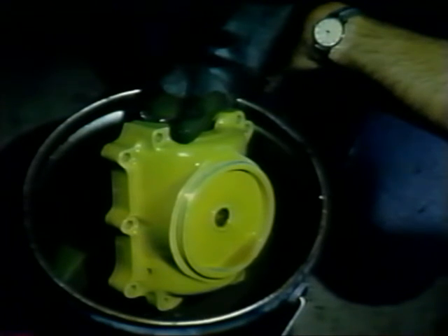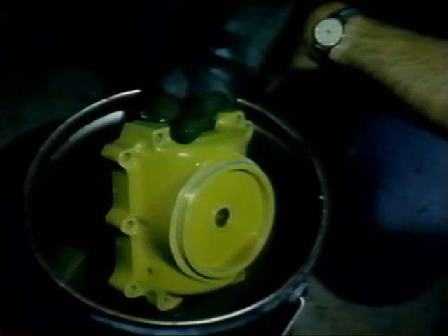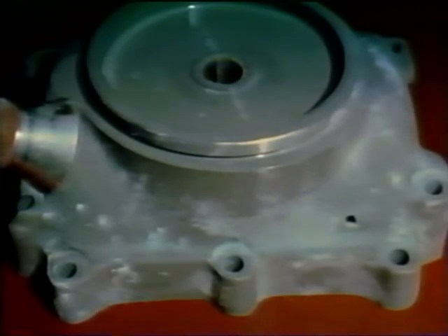Non-ferrous components of the hub are inspected for cracks using dye-penetrant inspection. Here the parts are immersed in the penetrant solution, then washed and blown dry with warm air. A powder developer is applied to the part to draw any of the penetrant that has been retained in a crack to the surface. Under an ultraviolet inspection lamp, the penetrant drawn from the crack will be clearly visible as a fluorescent line.